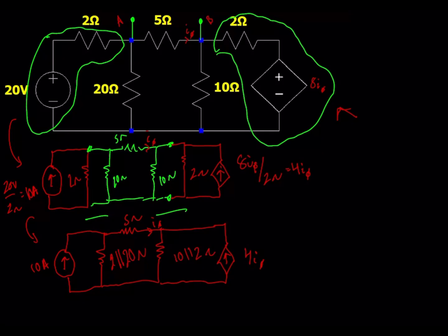So we can see that we've simplified from the original circuit considerably. Again, we're trying to find the Thevenin voltage, so that's still these terminals here from the original circuit. But now we're going to use source transformation again, because by simplifying these resistors, we can swap back to our original configuration.